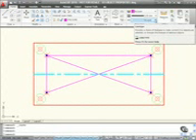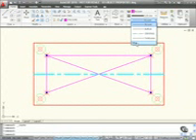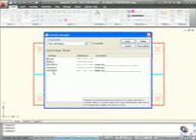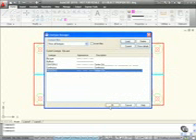It's by layer at the moment. I can load up a new line type by clicking on Other. So I click on Load there, and I'll load up, let's say, a hidden detail line type here. So there's hidden X2, where the dashes are twice as big. I'll OK that. Select hidden X2 there and OK it again.